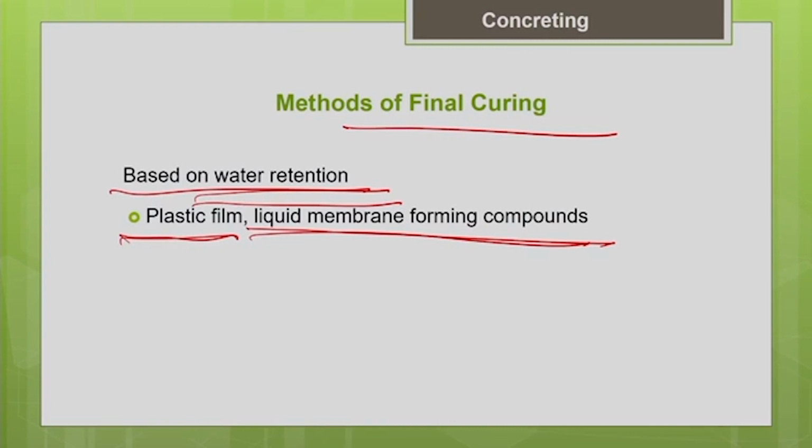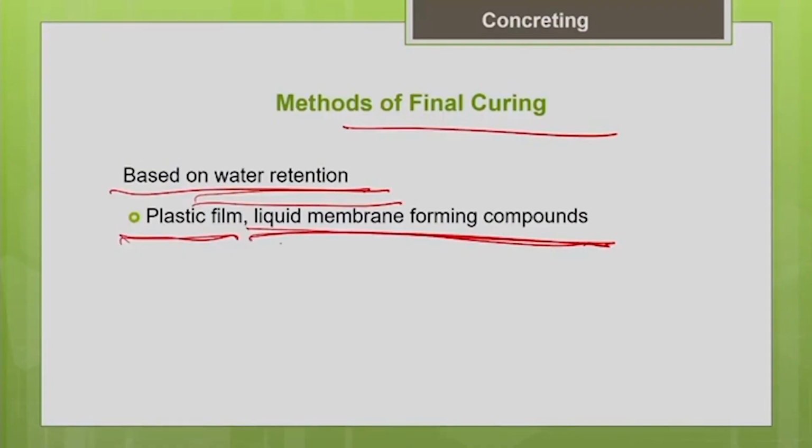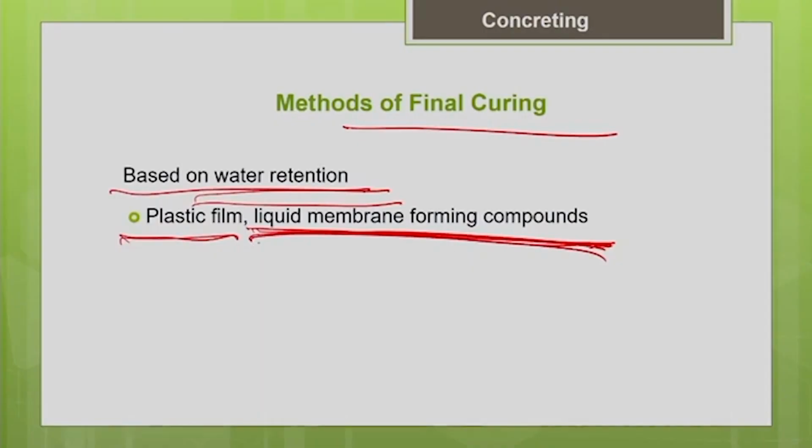Depending upon the chemical we use, it will facilitate the self curing of the concrete. That means it will prevent the loss of water from within the concrete to the outside environment. Another thing is this will not result in any staining, as we discussed for the evaporation reducers. There will not be any stain formation, and it lasts for a longer time, as I told you, even up to 28 days.